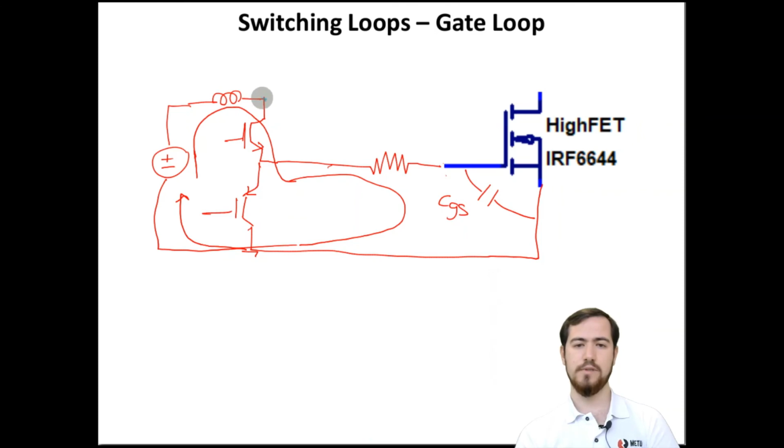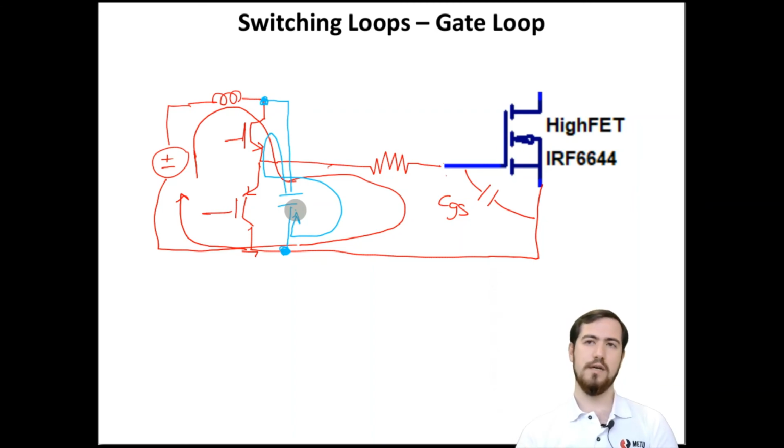For that purpose, we need to connect a capacitance from the power pin to the ground pin to supply the high frequency current for the gate driver. That is the path it follows. So the usage of capacitances is really important for reducing the oscillations and optimizing the layout inductances as well.